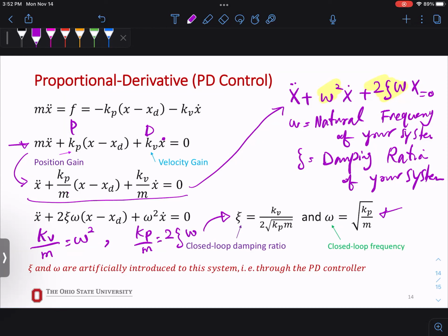So that is our first guess for our PID coefficients. We plug it in, we plot the response, and we look at whether this is what we wanted. If there is a slight difference, we can then adjust from there. So know that for a PID controller, you always have to tune, but for where to start, these two points are the best educated guess.